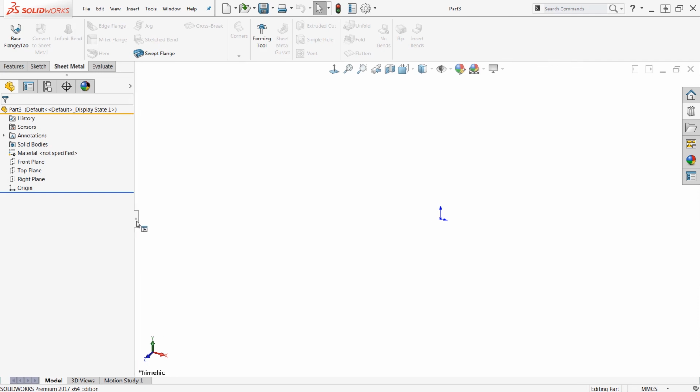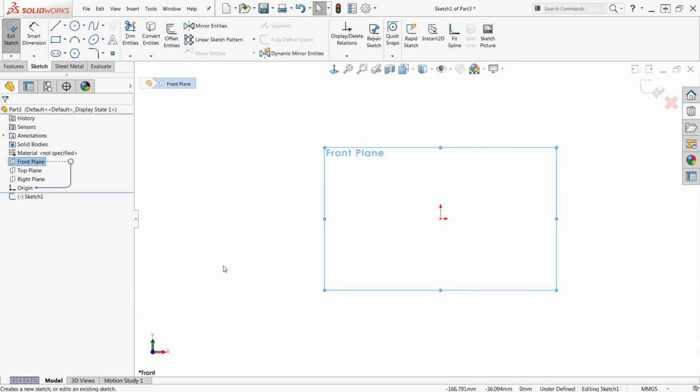The flange method for sheet metal design in SOLIDWORKS takes an approach for creating a sheet metal part based on its finished state. So we're going to create the overall profile of this. I'm going to go ahead and choose the front plane and begin a sketch. Now we've left 2D, 3D sketches. Now we're just into standard SOLIDWORKS stuff now, right? Two-dimensional sketch. I select my front plane, begin a sketch, and I've entered into that.